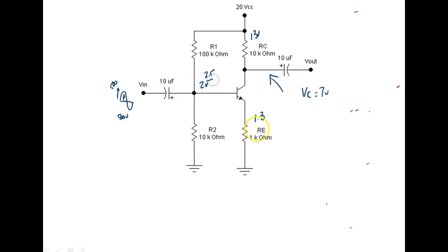If this goes up to 2.5 volts, now let's talk about bias. This guy can't move. I could heat this sucker up all day long with bias, and the voltage drop across this resistor right here wouldn't change. Because if the voltage drop across this resistor tried to go up, and I have this clamped at 2 volts, it can't go up, right? Because that junction's got to drop 0.7 of a volt. So this guy here will not go into thermal runaway. But what we're doing here is the input signal is changing the base voltage. Can that happen? Sure.